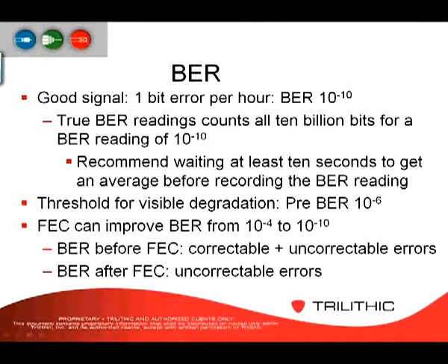Now, when you're looking at it as a true BER measurement, it takes approximately 23 to 25 seconds to look at a billion bits. So you need to look at it for at least that particular time so that you can base your readings off of a billion bits.